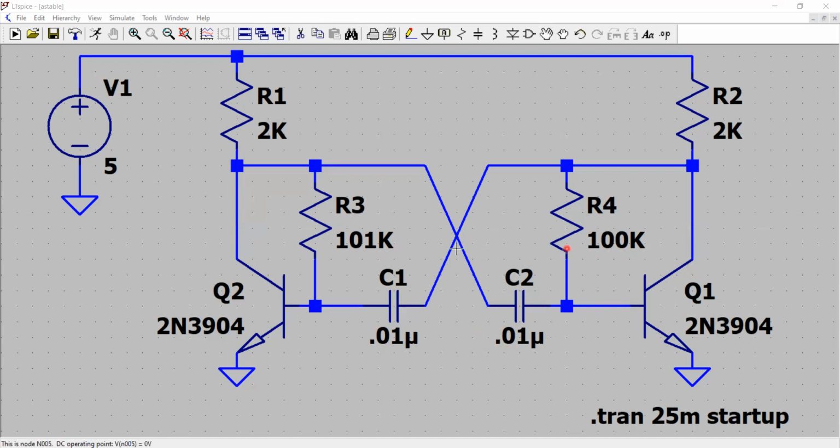There is a slight difference between the two. Write in the comments why that is different. Why are they not exactly equal? And what if we make them equal? Similarly, R1 and R2, the load resistances for Q1 and Q2, are also of the same value. We are using a 5-volt DC power supply.